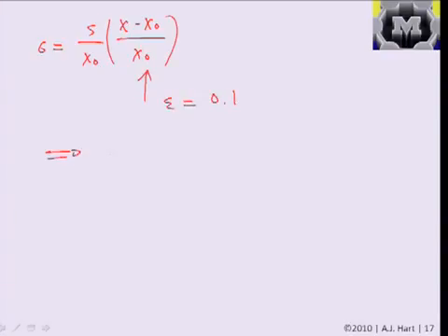Typically, if we looked at just this one bond and went back to the interatomic potential, we could say that at about 10% of the separation, or about 10% elongation, the atoms would no longer feel each other. So the bonds are going to break at about 10% elongation. If we went back to our original expression for the stress, where we had S over x naught times the strain, and said they're going to break where strain is about 0.1, then that would directly tell us that they'd break at about 0.1 times the Young's modulus.